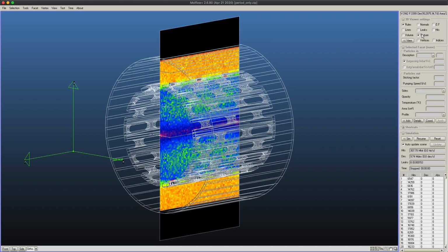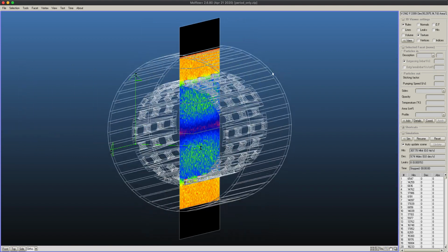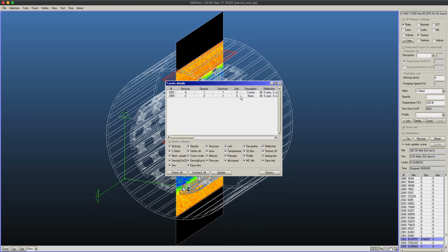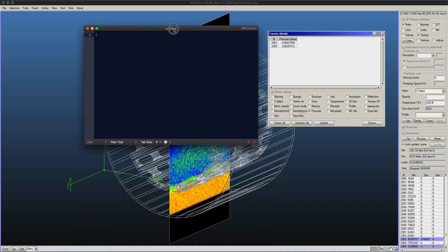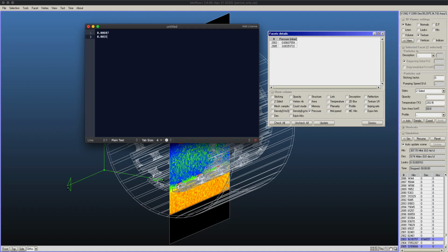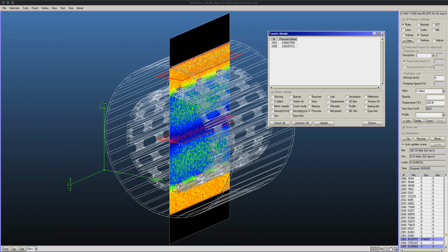So what I will do is, first, I have created 2 profiles here. I will just check what the pressure on them is. So you can see that it's about 6 times 10 to the minus 3 and 3.5 times 10 to the minus 3 millibars. And I will just simply note down those values: 0.00607 and 0.003517. Don't forget that Monte Carlo simulations are not infinitely precise.